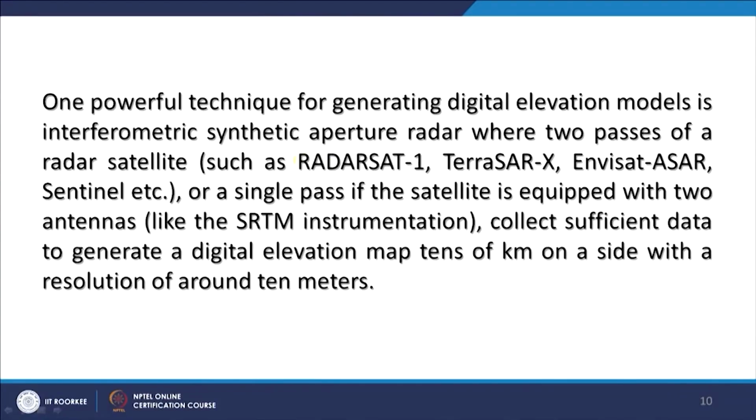And this SAR interferometry technique for generation of digital elevation models basically started with the satellite called RadarSat, because that allowed creating a pair, not a stereo pair but a radar pair, and later on, using this interferometry technique, digital elevation models were prepared.